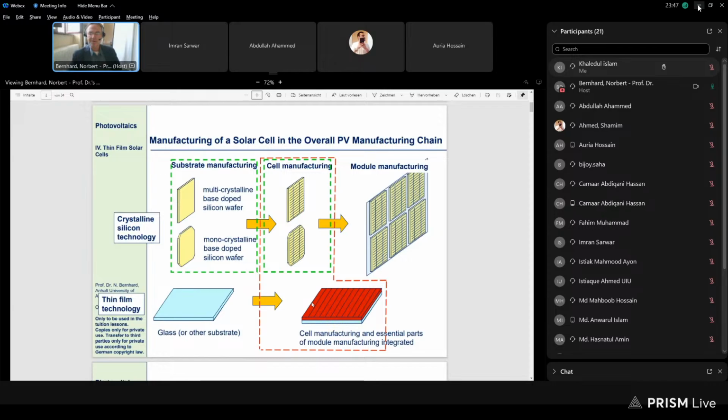Okay, let me first show the band diagram of the amorphous silicon, and actually you saw it already in the second lesson as an example for a drift-determined cell, and it's actually the only purely drift-determined solar cell. This is the purpose of the intrinsic or undoped layer: to extend the electric field, which is usually limited to the space charge region of the junction, across the whole cell.